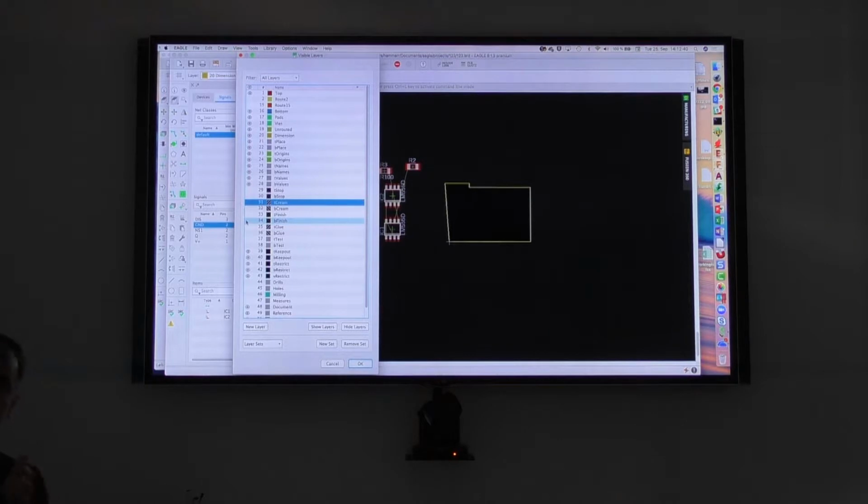You want to mount it and unmount it, you have a connector. And in some cases you want to have these contacts plated mostly with gold, because that's very resistant and has a good mix with contacts. So you need an additional layer where you draw the mask for the gold plating, for example. So that's the finish layers or whatever it is.